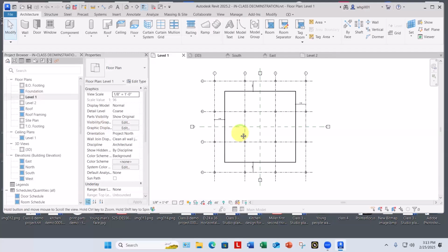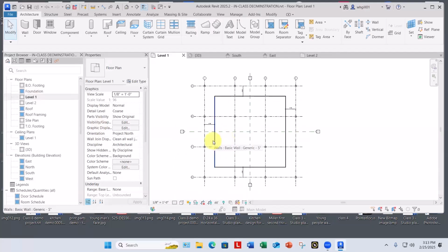I need to go back to level 1 so we can insert that PDF image that we just downloaded that has what goes on in here on the first floor. And we'll just get close, not getting it perfect. And that's a PDF. So we imported the CAD drawing and placed it here. We don't have a centering device for the PDF, and we don't know how big it is. So we're going to have to expand it to be, that's 126 feet column to column, and then place it in place. So 2 steps here.